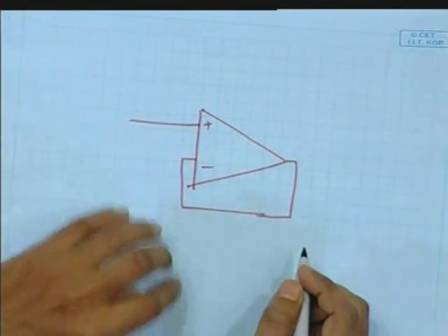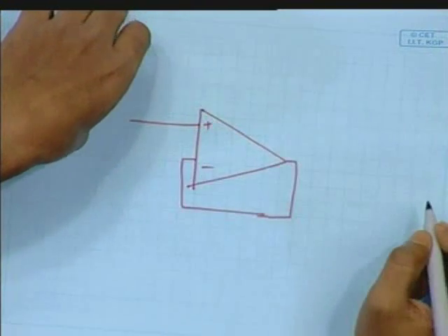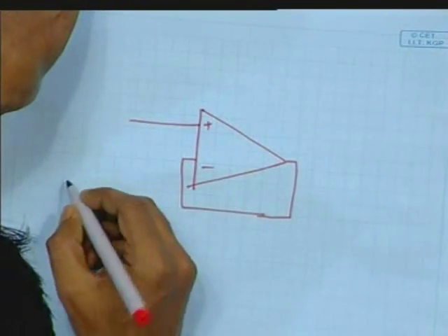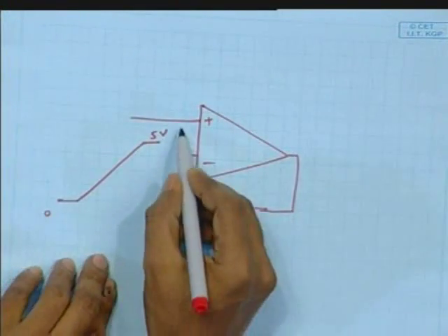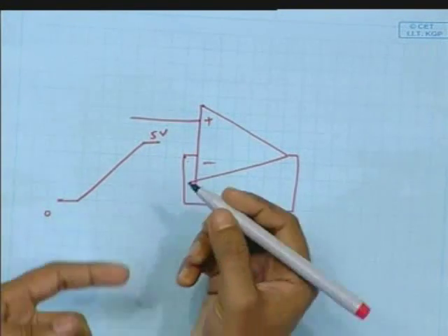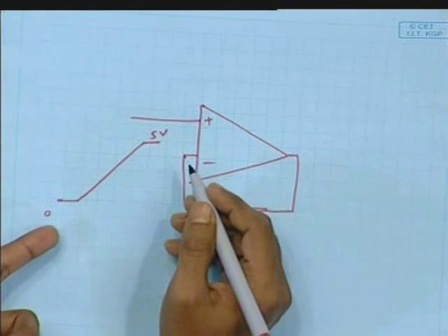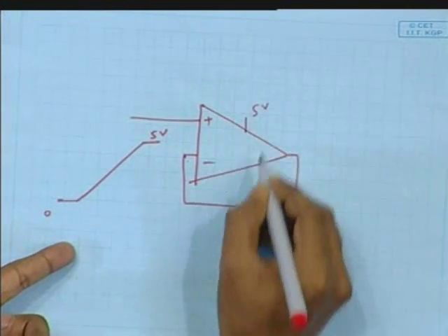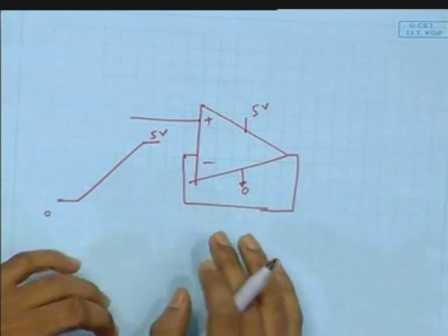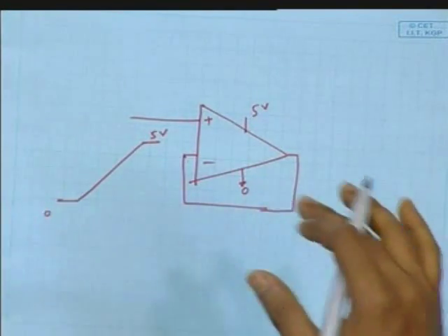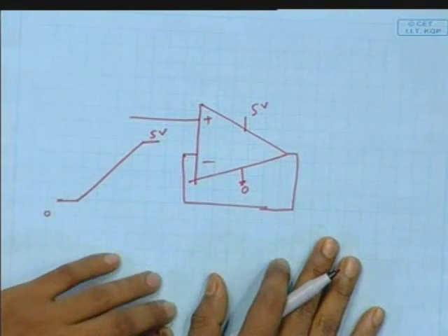Right. But when we are using the op amp, we have to choose the proper op amp, right? Because here you can see this signal level is considered 0 to 5 volt. This is an analog RAM signal, so this node is also following the same signal. That means the common mode level is 0 to 5 volt. The supply of this is 5 volt and this is 0 volt. That means the op amp should have rail to rail common mode level. So for that we have to use both N pair and P differential pair, then combine both. Okay, those things will come. This is a simple unity gain buffer to receive or transmit an analog signal.